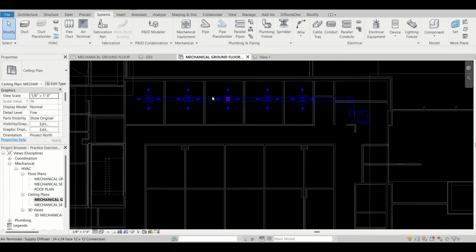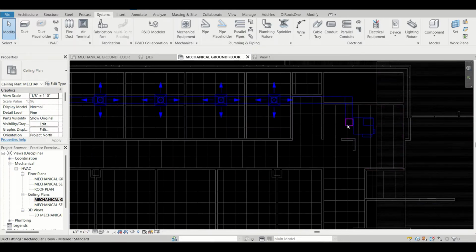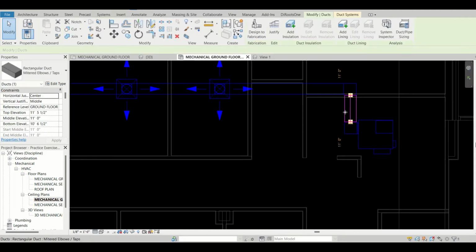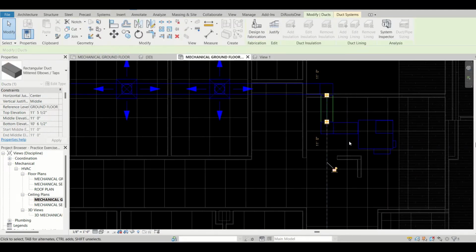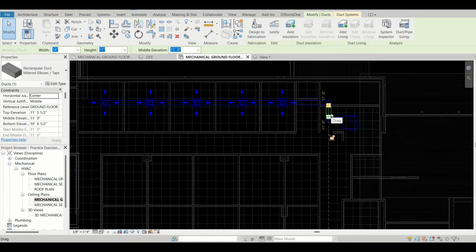Now it's properly connected, with zero warnings, no warning has come. After modeling by the generate layout command, you can also change the parts if you want. Right now I just moved this duct, but as of now this has been done automatically. We did not give any design command to this one. So the duct size is not properly settled, so we need to resize the duct networks.